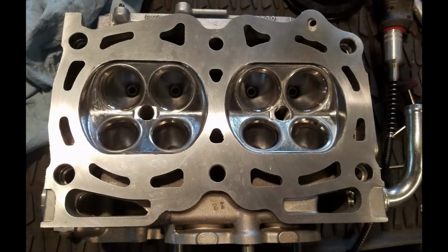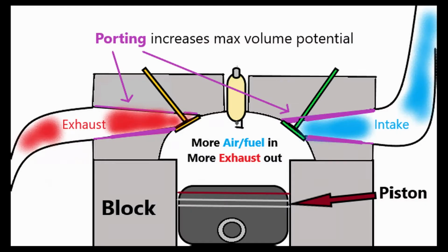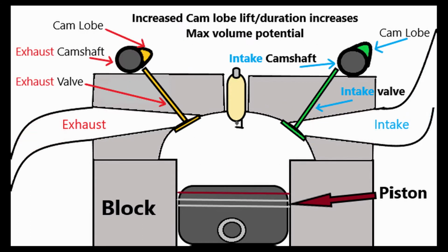Now let's talk about supporting engine head upgrades. For heads, there are two main things that are done to create more power: upgrading the camshaft or shafts and porting/polishing. These two modifications essentially do the same thing: increase the max volume of fluid that flows into the combustion chamber. Remember, air is treated as a fluid in fluid dynamics, and we can save the discussion about air velocity and turbulence at another time.